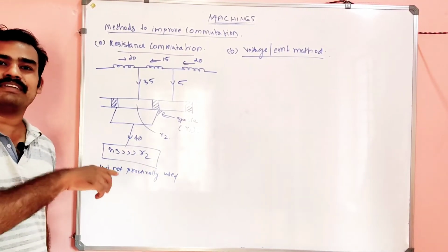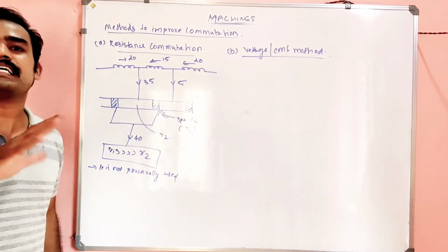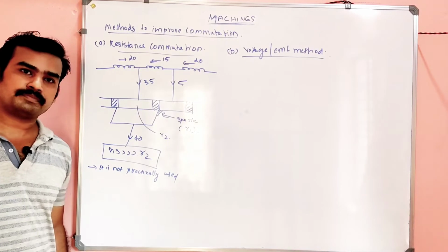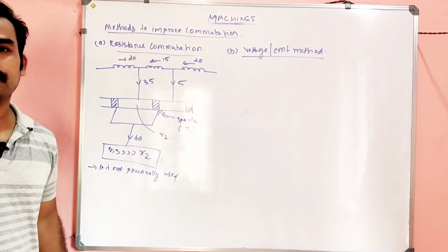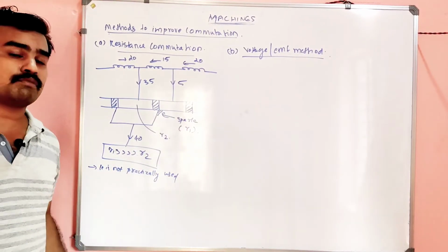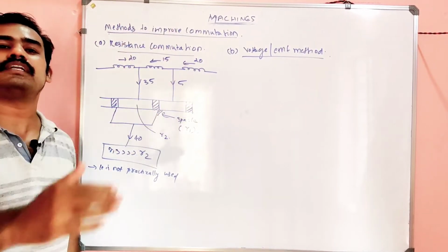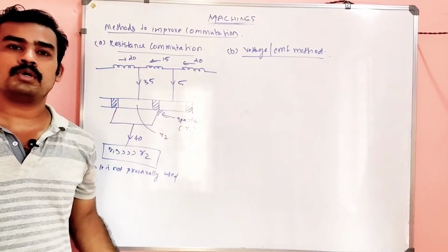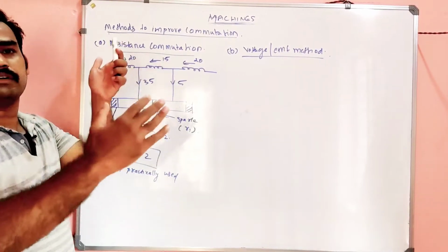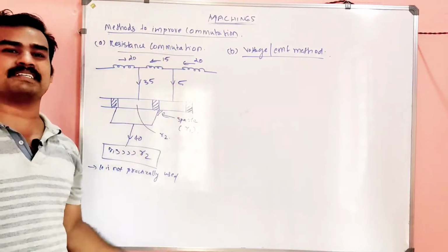Because I already know the reactance voltage. What is the reason for producing that reactance voltage? The change in the current in the armature coil, my dears. And that current is not perfect; there is a loss. The reason for the loss is the imperfection or non-uniform distribution of magnetic flux in the pole faces or pole region. That is the reason there is a tilt or inclination of flux lines in the main field flux, and that is the reason for the armature reaction.